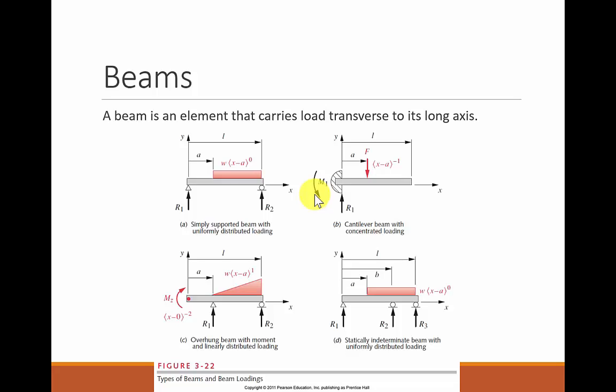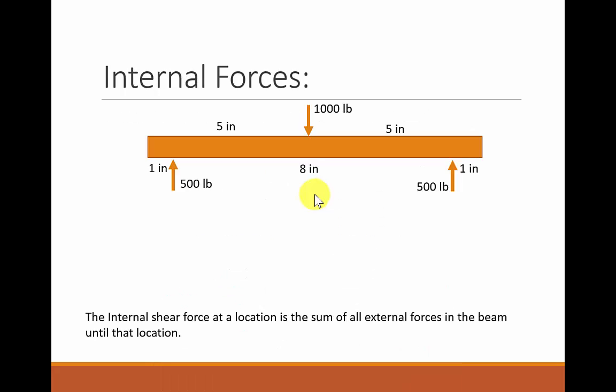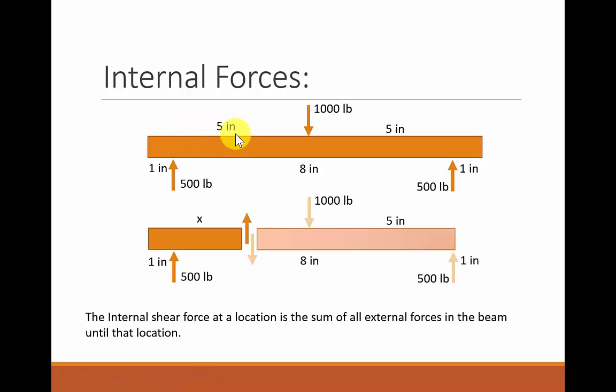Another concept we need to remember is what happens on the inside of a beam. So at the end of the day, what I care about is the stresses that are occurring within a part. And so to take a look at that, let's consider what would happen if we break this part into pieces. So what we're really going to do is make a free body diagram of part of the element. So let's say we break it maybe somewhere right in here. We're going to say the distance from the beginning is now considered x. So we're breaking it at x.